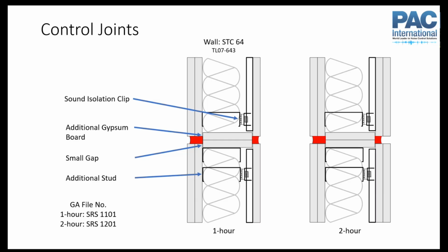And then you would often put a plastic control joint trim piece over this or something like that. But you want to make sure that this gyp that's on the stud, again, we're trying to seal a cavity path, but we want to make sure that we don't create a rigid structural path here. So there needs to be a very slight gap between the drywall on the face of the wall and the drywall that's there on that stud. So there's not actually a rigid connection between them. You need to pay attention to that little detail. But by doing that, you seal that potential path there.